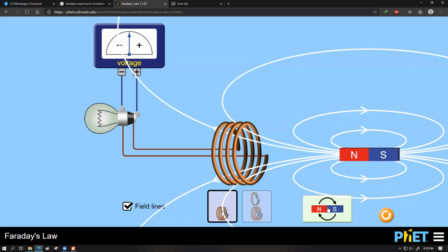The third observation for Faraday's experiment was this. First, I'm going to repeat the first once again. The first one was that moving the magnet, as long as the movement happens, induces the EMF. Movement stops, no EMF. That's the first observation. Second observation, reversing the pole orientation or the movement direction reverses the EMF induced in the coil. Third observation, faster movement gives more EMF, slower movement gives less EMF.